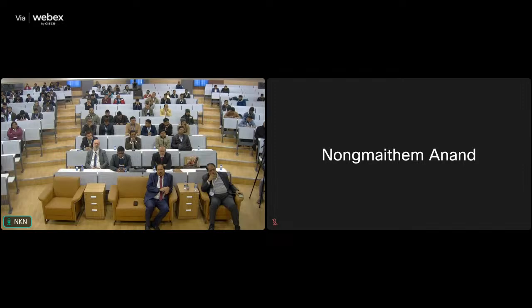So we have rock bolt and shotcrete support. We have already inserted the rock bolt, so there is no chance of changing the bolt spacing. Now, since the support pressure we expect because of the rock bolt grouting is reduced, how can we manage that? By reducing the shotcrete thickness. So it leads to reduction in the shotcrete requirement.